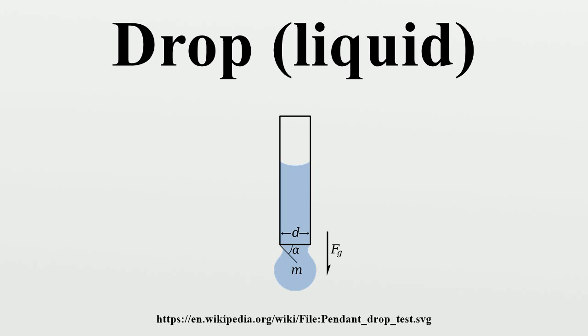Shape. The classic shape associated with a drop comes from the observation of a droplet clinging to a surface. The shape of a drop falling through a gas is actually more or less spherical for drops less than 2 mm in diameter. Larger drops tend to be flatter on the bottom part due to the pressure of the gas they move through. As a result, as drops get larger, a concave depression forms which leads to the eventual breakup of the drop.